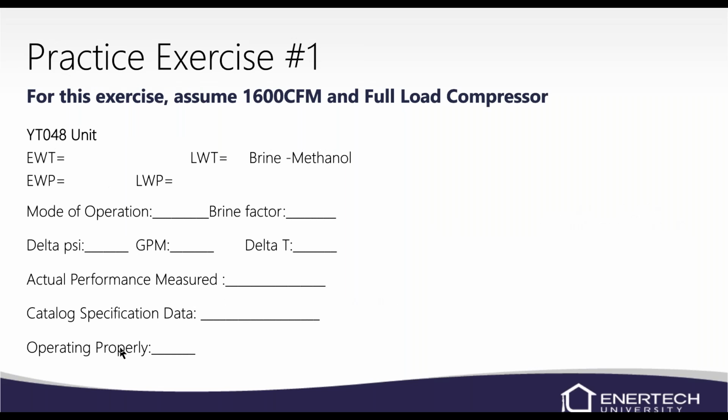So we'll go through a couple practice exercises here real quick. A lot of times I know we're going to give you CFM levels and it lists those in the IOMs. It doesn't really change the BTUs that much. So if you don't know what your CFMs are, don't really worry about it too much. It may affect your BTU output by 1,000 or so, but don't worry about it too much unless we're outside of that 10%. Then that'll make us look at other things. So we may look at the airflow at that point.